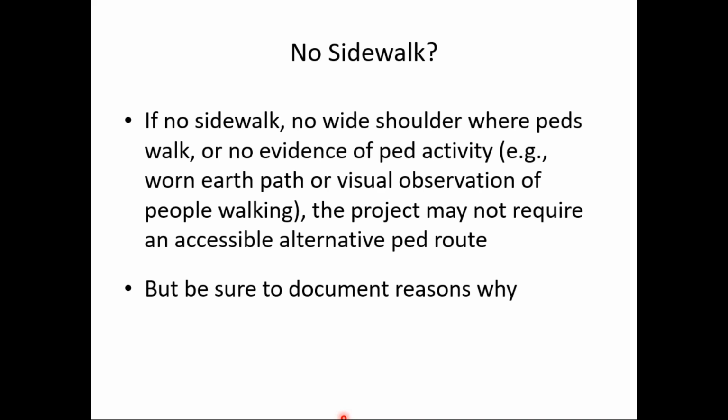But what I would also probably do is have somebody on the crew designated to be on the lookout for, and if they see mobility impaired pedestrians, say someone in a wheelchair, to be able to assist that individual and get past the work area. Because I am always surprised, I probably shouldn't be surprised, but as you all know, West Virginia is a relatively rural state once you get outside our built up urban areas. And I've been on some really low traffic volume secondary roads in the state and come around a corner and there's someone in a motorized wheelchair kind of scooting down the road. And that's great for them. But my point is sometimes even when we least expect it, there may be a mobility impaired pedestrian in the roadway. So even if we're not providing facilities, we need to make some sort of arrangements so that if somebody does show up or appear, we have a plan to get them around the work area.